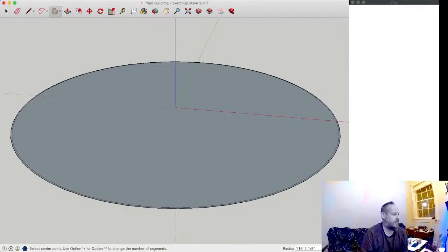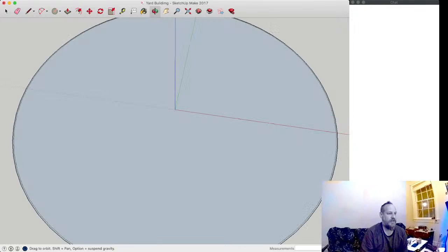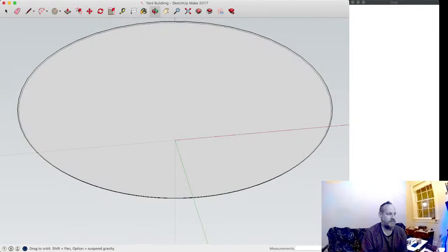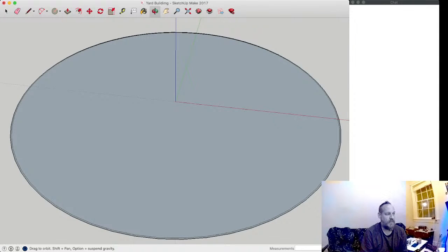Now, here you see a gray ground plane, and on the bottom it's white. We need to reverse those faces. The reason we need to reverse those is that a white plane means that that's the mesh side that you could touch in Spatial. The gray side, everything just passes through it. If you don't pay attention to adding color, you might not see the object that's there. So here's what I'm doing. I'm right-clicking on that face. This menu pops up. And just go to reverse face.